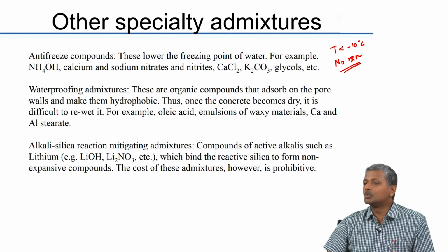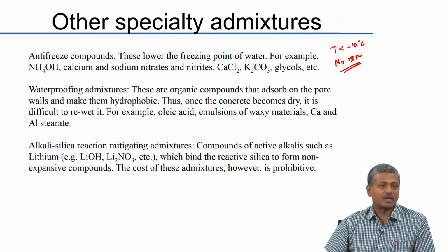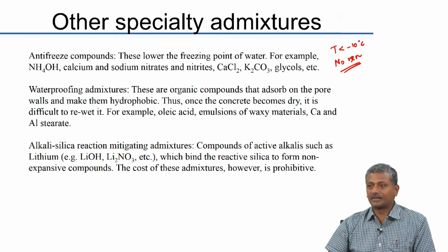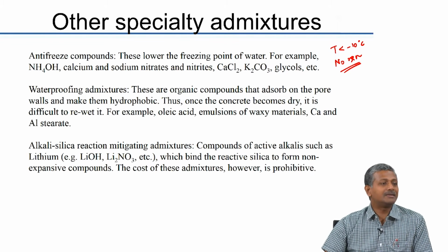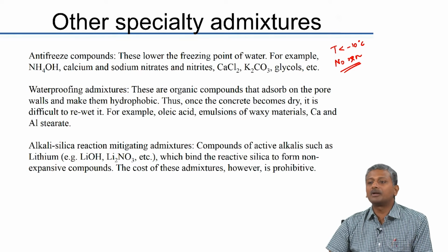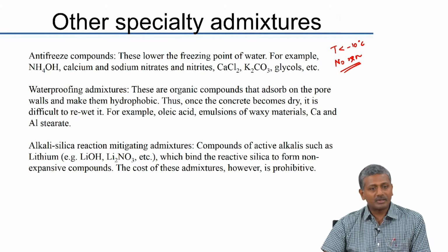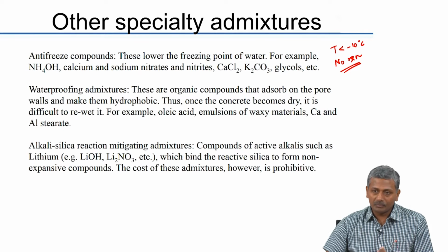What do you intend to do with that? When you add these chemicals, what do you think is going to happen? Water won't freeze, exactly. There will be no freezing of water, because of which you will maintain the reactivity of the cement water system. So, they are basically freezing point depressants. All these chemicals will depress the freezing point and prevent the freezing of water, that enables the interaction of water and cement.